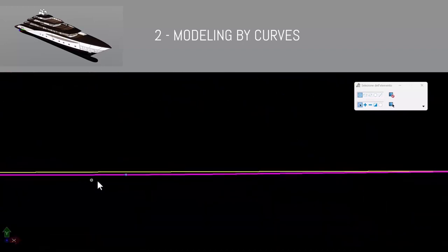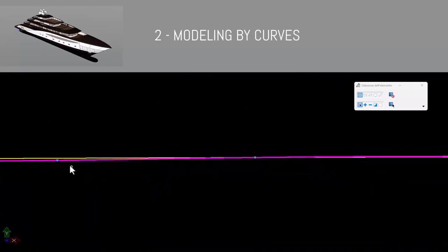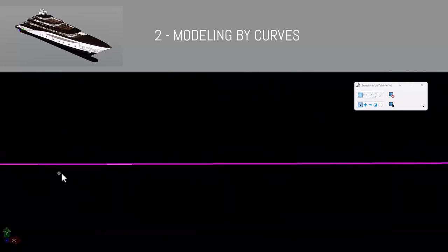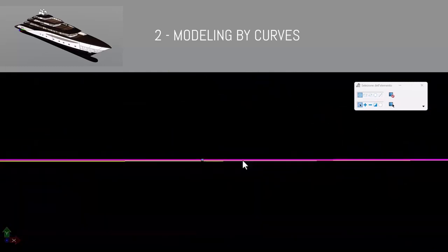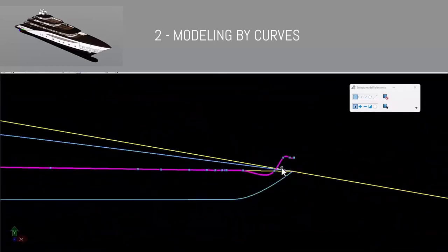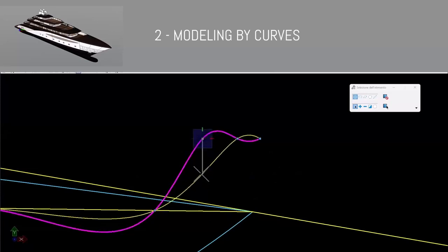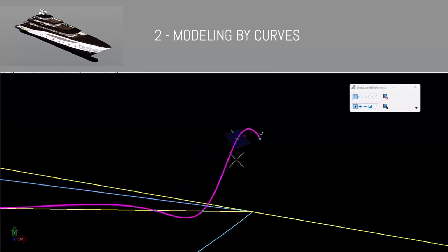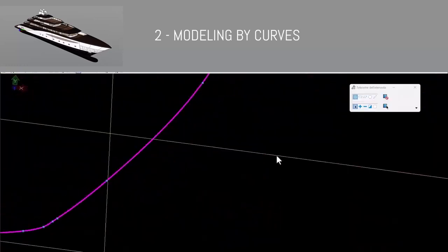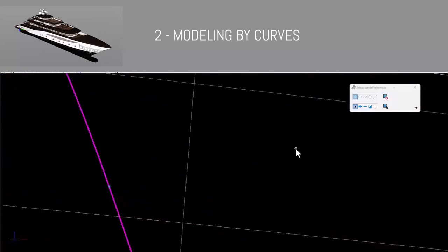This model has been conceived with some guidelines and sections that have always been a reference for the predetermined final goal. Curves can also be extracted from existing surfaces. This is particularly useful when you need to complete starting from a certain surface, because the extracted curves can develop on three axes, becoming difficult to manipulate. But in MicroStation, there is a very practical tool to flatten a curve on a desired plane, and this allows you to proceed in the design with greater ease and precision.